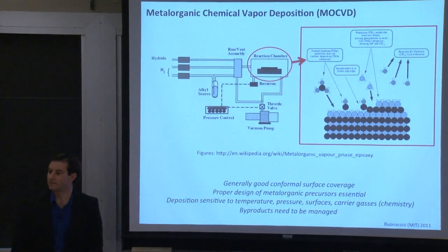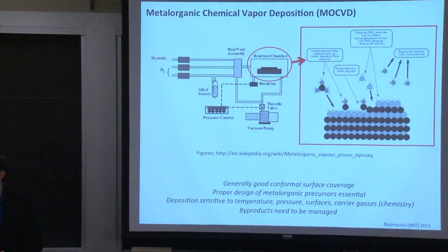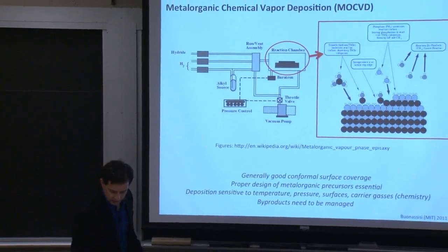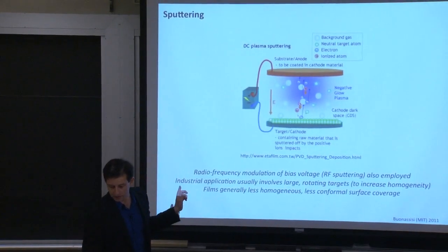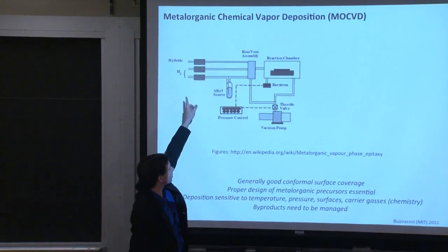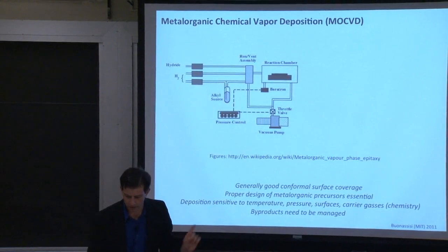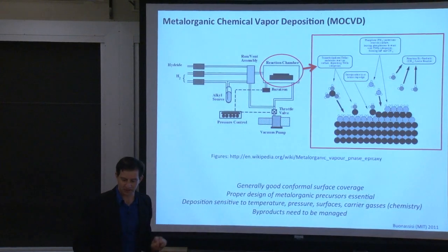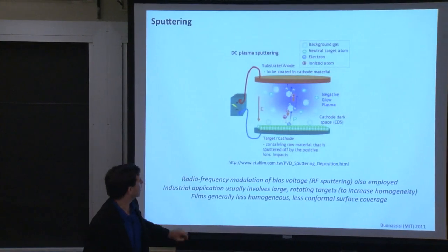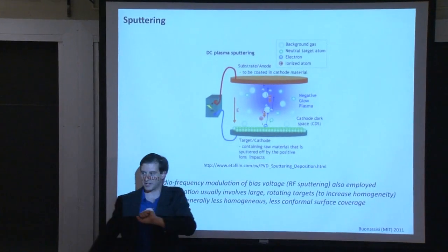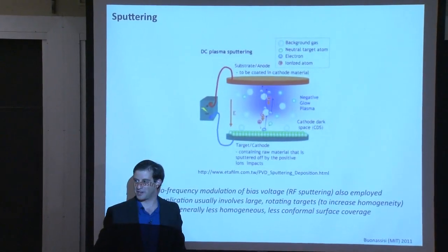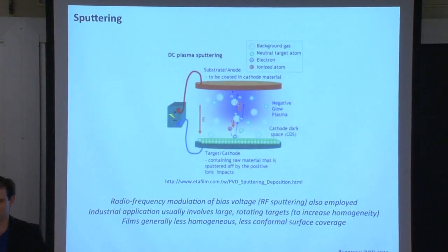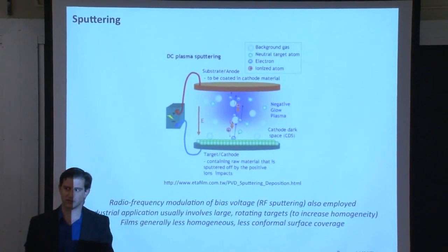Yes? And the purity is much better for MOCVD than it is for sputtering, right? It depends on a lot of factors. The reason the purity of MOCVD is generally better than sputtering is because the mass flow controllers necessary to control the gas flow are specific for particular types of gases. Now in sputtering, because of the versatility of the sputtering chamber, you could take this target out and put in, maybe Ashley comes along into your sputtering chamber and she puts in another target of another metal. And now you're depositing two different metals in the same sputtering chamber, you're going to get cross-contamination.